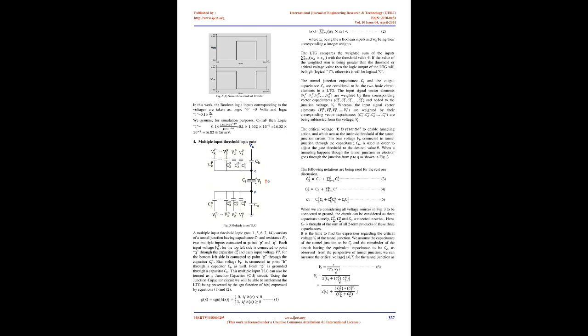The inverter [1, 7] is made up of two SETs connected in series as depicted in Fig 2a. Two input voltages of the same value are directly coupled to the islands of SET1 and SET2 through two physical capacitances C1 and C2 respectively. The island of each of SET1 and SET2 has a size smaller than 10 nm of gold and their capacitances should be less than 10^-17 F.